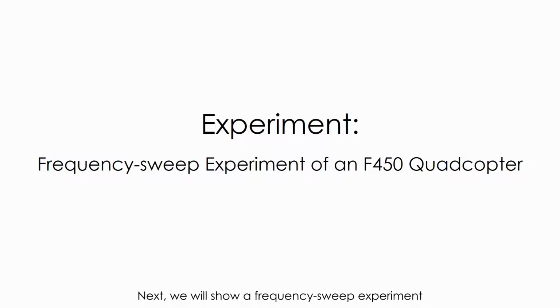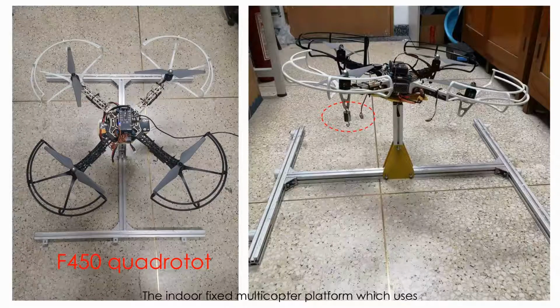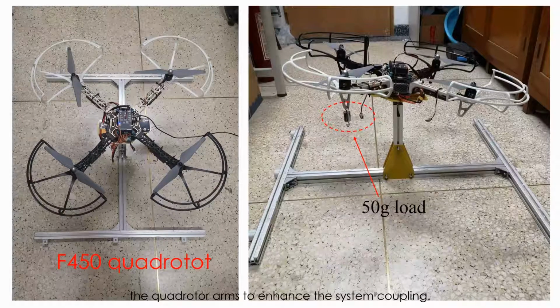Next, we will show a frequency sweep experiment of an F450 quadcopter. The indoor fixed multicopter platform uses a specially built stand to restrict the motion of the quadcopter to 3 degrees of freedom without position change. Additionally, a 50 grams load is attached to one of the quadrotor arms to enhance the system coupling.